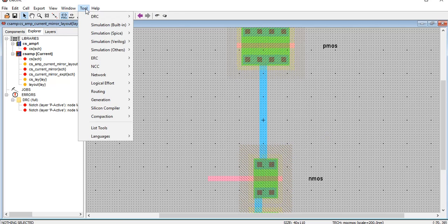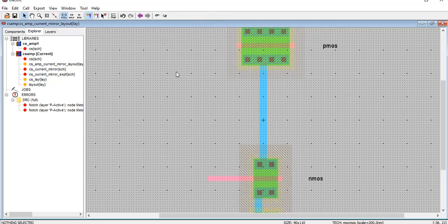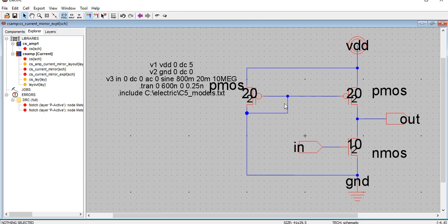Yes. Once again, let us try to run DRC, no errors. Fine. So, now what exactly we require here, this portion is done, now I require this portion. So, this portion can be constructed how? I need to again place one more PMOS, and this I need to be connected in the diode connected form.